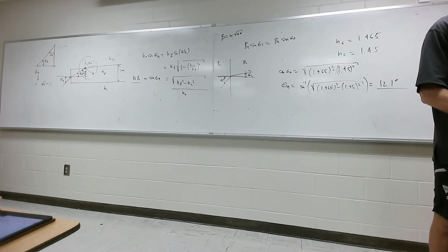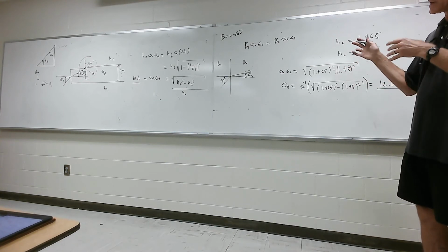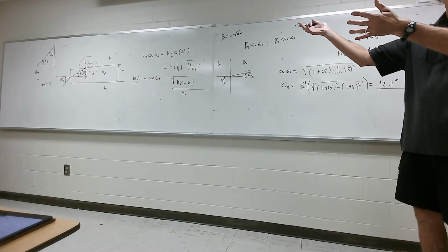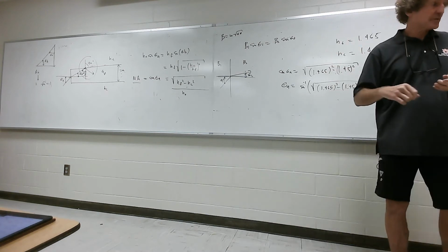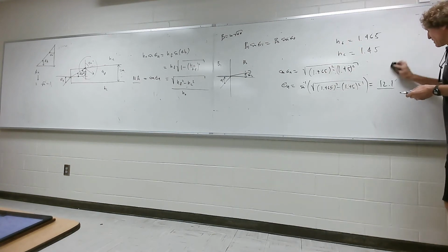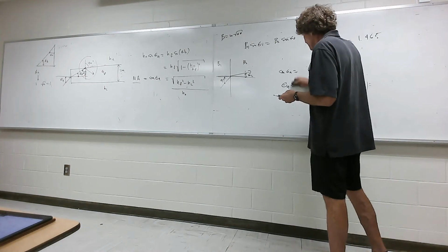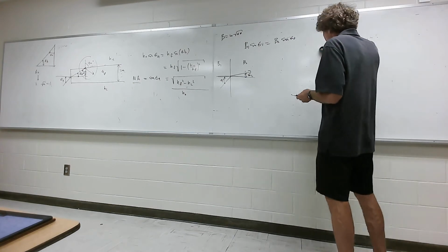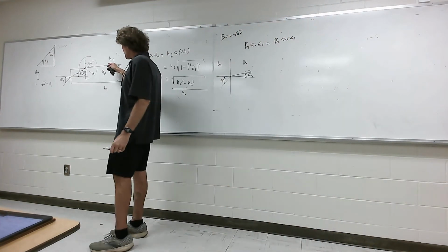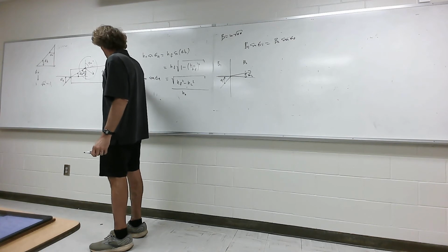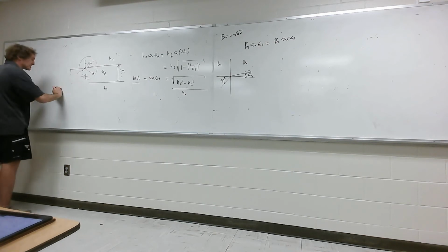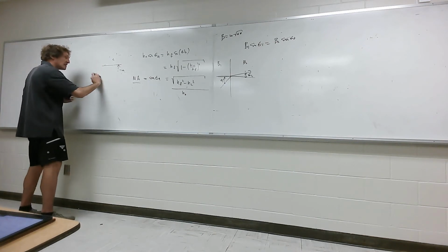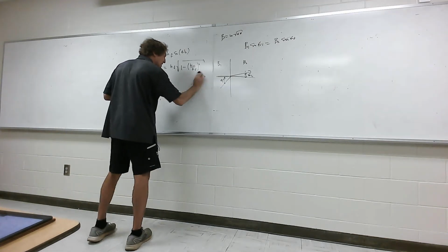A few other things I'm going to mention. For the single mode, when we're talking about circular fiber optics, you want only one mode, right? Now, remember, and I'm going to erase this and show it up here. When you talk about one mode, and this is step index fiber, graded index, it means there's a discrete change from here to here, and it's assumed constant, then it goes from here to here, it's constant above it. But this is where it gets interesting.